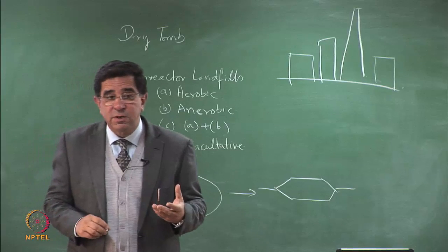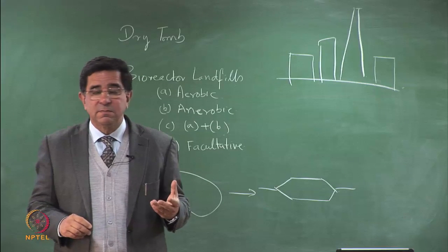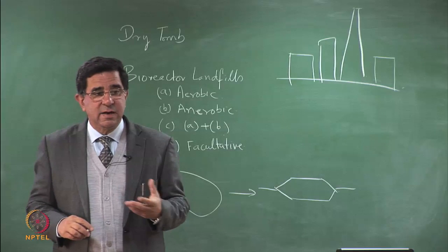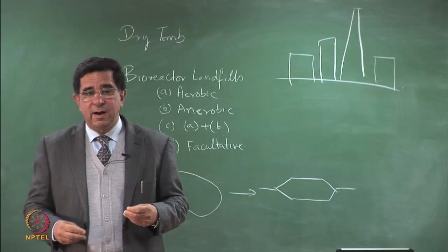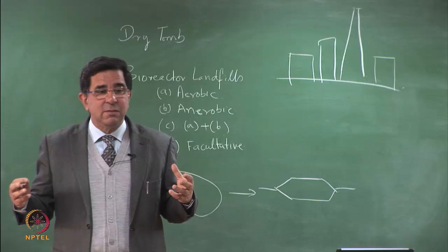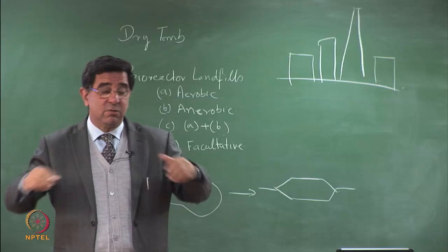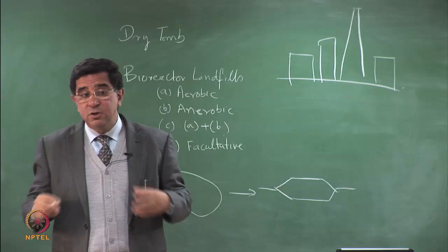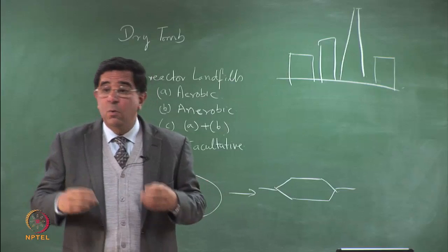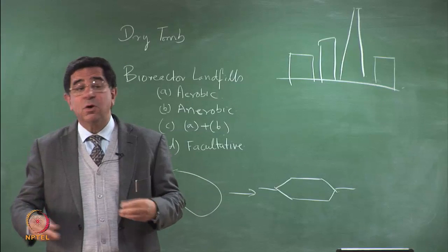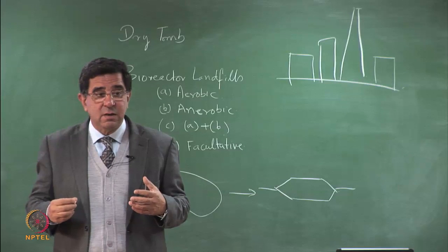I said if you do windrow composting, in how much time, windrow composting is aerobic. In how much time does the waste stabilize? Do you remember that I had said that you can make these long windrows, you can turn them over every day. Well, I said in weeks, the waste will stabilize in weeks, right? And remember, windrow composting is also open, and so they should put it under a shed. It's not containerized composting. So containerized composting is more expensive. Windrow composting is less expensive but gives more odor. But in any case, we are talking here of stabilization of the waste in weeks.